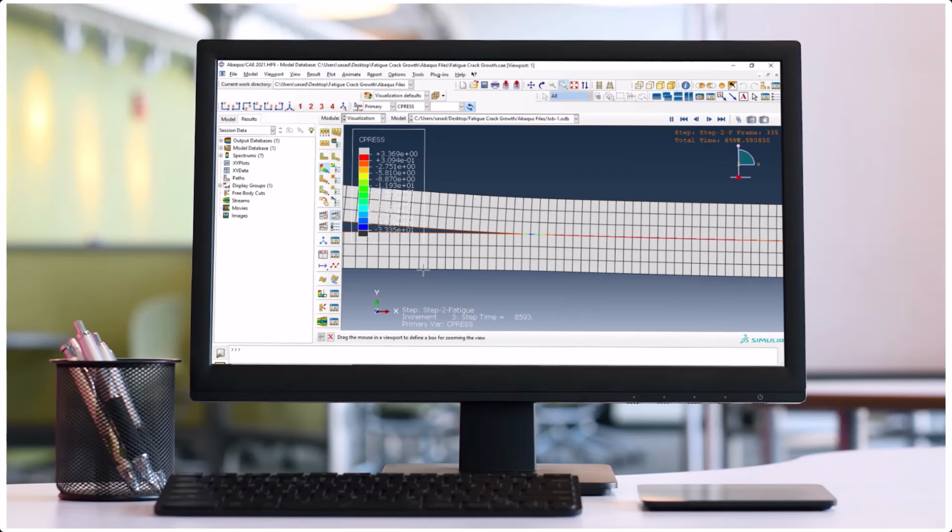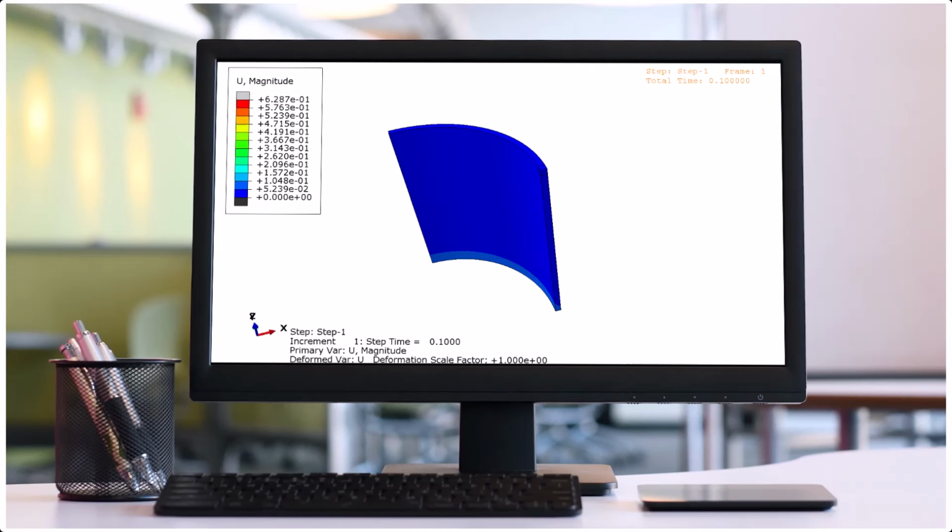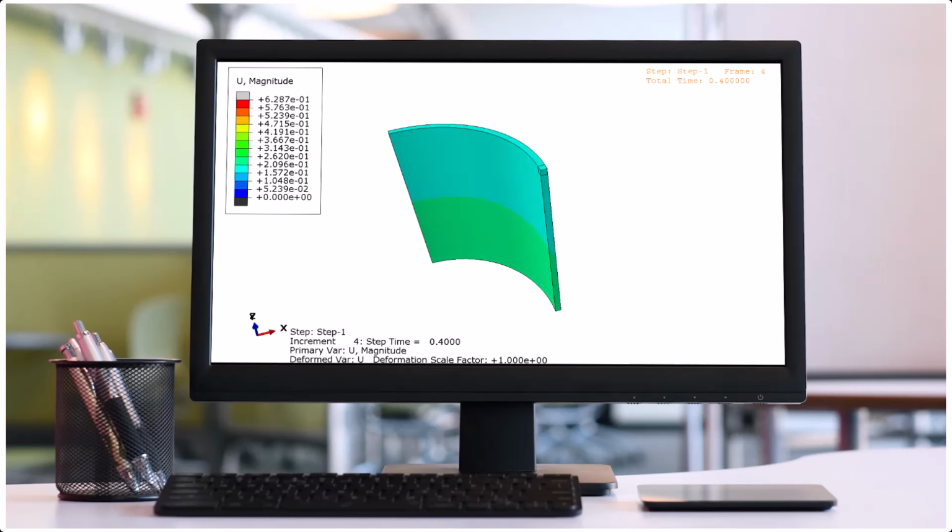In Workshop 7, we simulate a tank with a crack, subjected to both internal and external pressure. This simulation uses the D-load subroutine to apply the load and the contour integral criterion to model the crack. The workshop concludes by showing how to extract the resulting J-integral value.